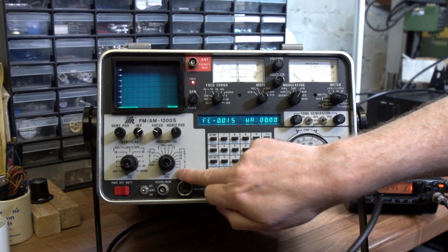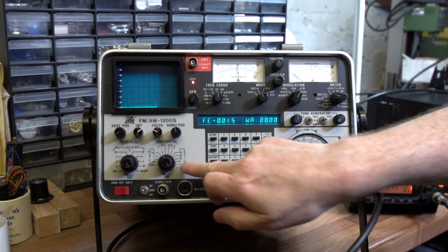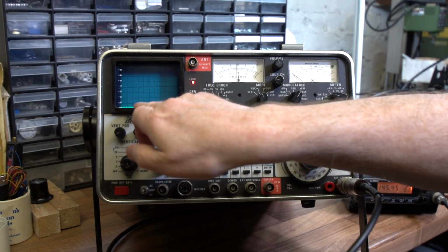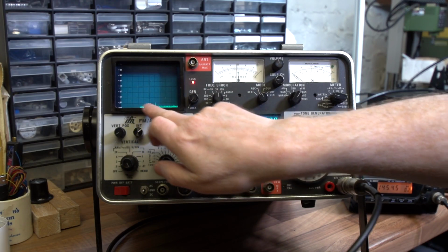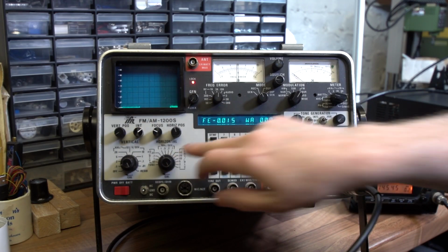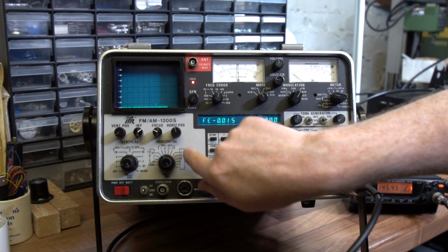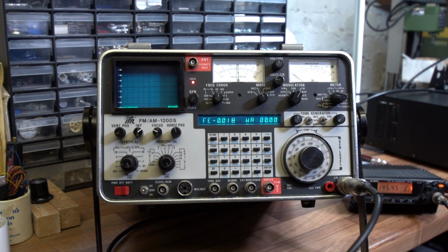This is our span control, how many megahertz per division we're displaying, and at the moment I have it set to 1 megahertz per division, which is giving us 1, 2, 3, 4, 5, about a 10 megahertz total span, like minus 5 megahertz to plus 5 megahertz, and that's the widest this goes. But you can adjust this and tune right in for a much tighter resolution, a much smaller span, down to about 1 kilohertz per division, which is great for looking at audio frequencies within the carrier.